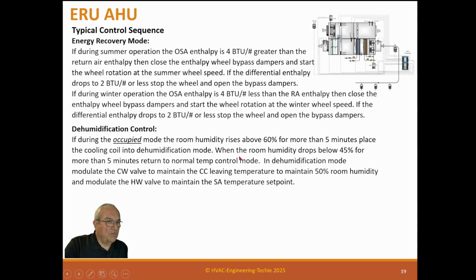Now, what we normally do here, some people have a sequence where they just want to drop the cooling coil to maximum cold, and this one will do it while the room is high, but as the room starts to drop, we want to maintain it to 50%. If you don't do this, then you will overcool the air and reheat the air, and you'll waste energy. There's no reason to do that. I mean, you might as well use the sensors you have in place to do a more logical reset that gives you some energy savings.